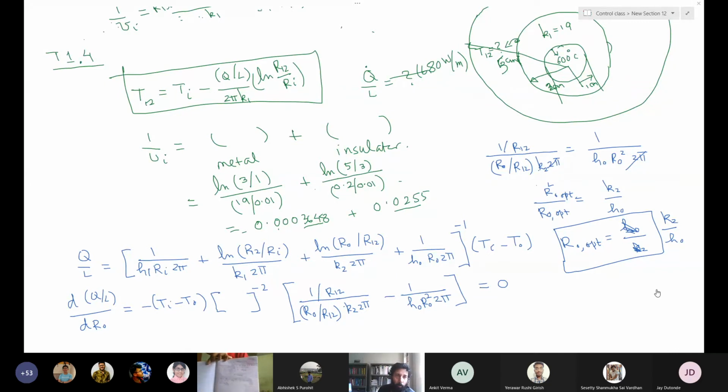Okay, what is the plan, Snehbandhu? So the plan is to write the total resistance and find the rate of heat transfer. The total resistance for the spherical case is R2 minus R1 divided by 4 pi k R1 R2, and the convective resistance also. From where did you get this expression? Did you derive that or learn it somewhere? I derived that just now.